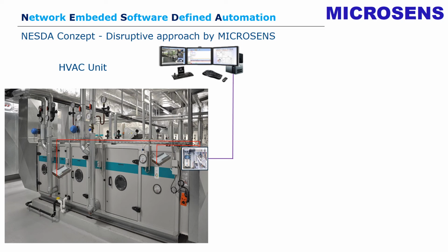So you see we run a switch locally on the ventilating unit, connected via uplink to the management layer, and doing the automation by running a program on the locally installed soft PLC. So this is an example of how we eliminate the conventional cabinet for running the automation for this ventilating device by using this smart distribution box.